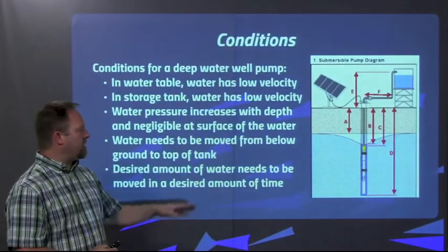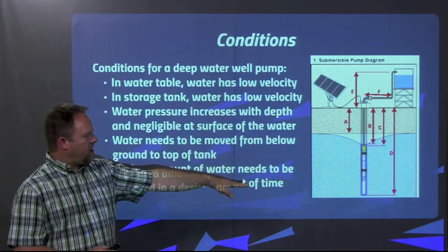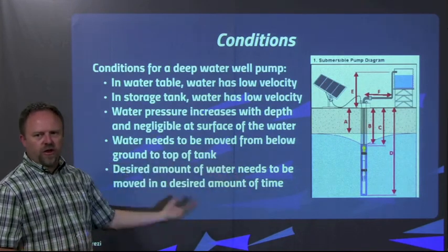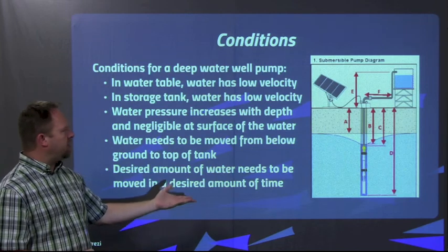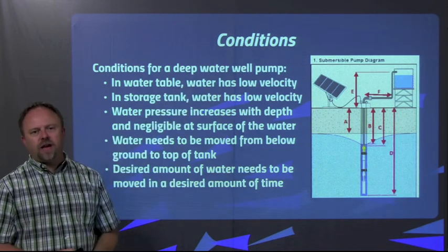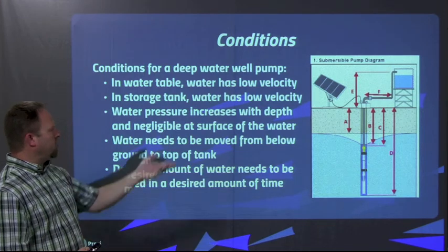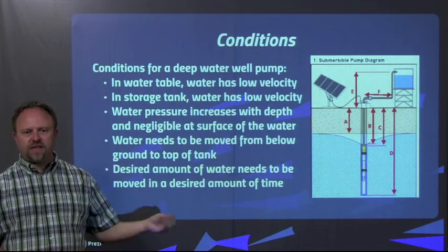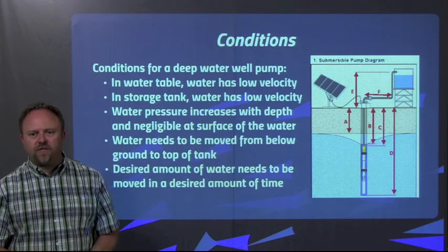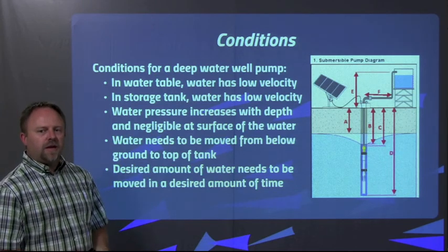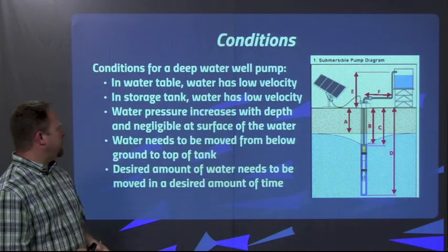So if we look at the conditions that we have underground, the water really isn't flowing a whole lot, so it has a very low velocity there. Also in the tank, we're dumping the water into the tank, but the tank water is pretty much still, so we don't really have much velocity at the intake or the exit of the pipe. So those terms will be negligible.